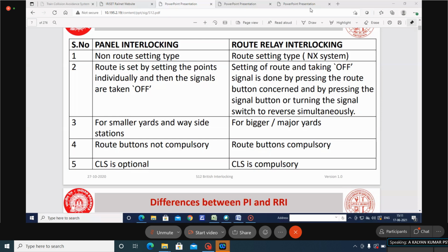So all these conditions we have discussed so far are normally satisfied. You assume that your route is free and no signal has been cleared. All routes are free. Then the signals associated with that point, the ASRs, are in up condition. The point zone track circuits are in up condition. The crank handles are in and locked condition. And the SM key is also in. All these conditions are normally satisfied. Will the point automatically operate itself, because the conditions are satisfied? We have to operate the point. Yes. The SM should turn the knob from normal to reverse or reverse to normal.